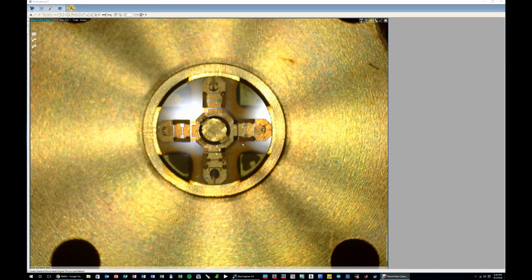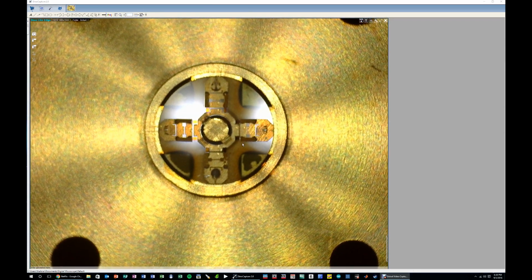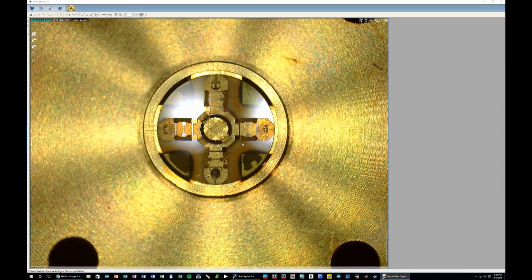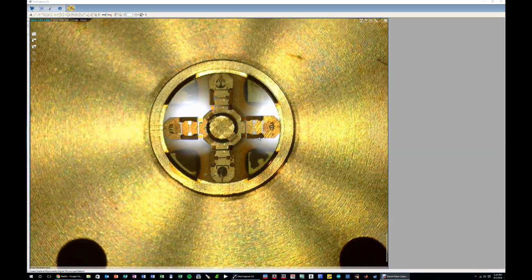Now if I look at the other one, which is the step recovery diode itself, which is also really cool. And this one, as we would expect to see, has the 4 outputs. So we have 4 diodes, 1, 2, 3, 4. Here's the input signal coming in, very large amplitude, hitting the step recovery diode. And then there's 1, 2, 3, and 4 outputs, which are the impulses coming from the step recovery going on to the sampler module. So really neat to take a look and see what's going on in there.